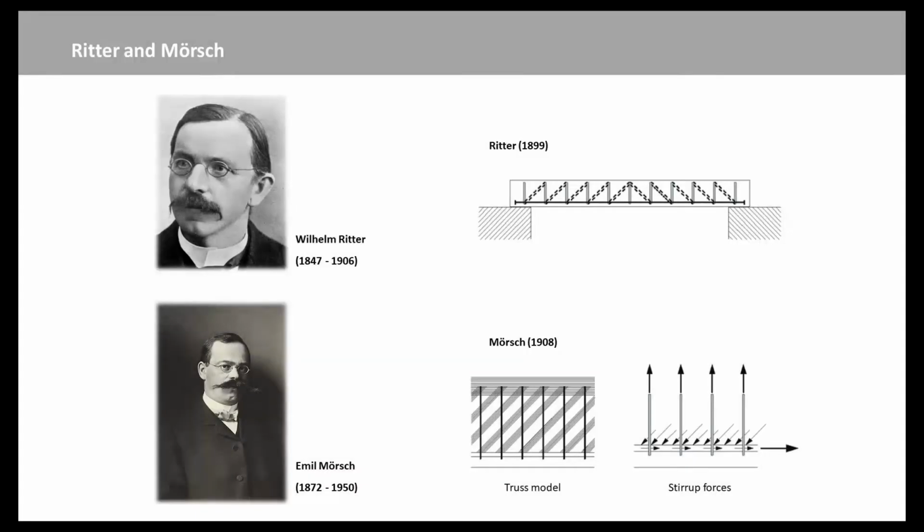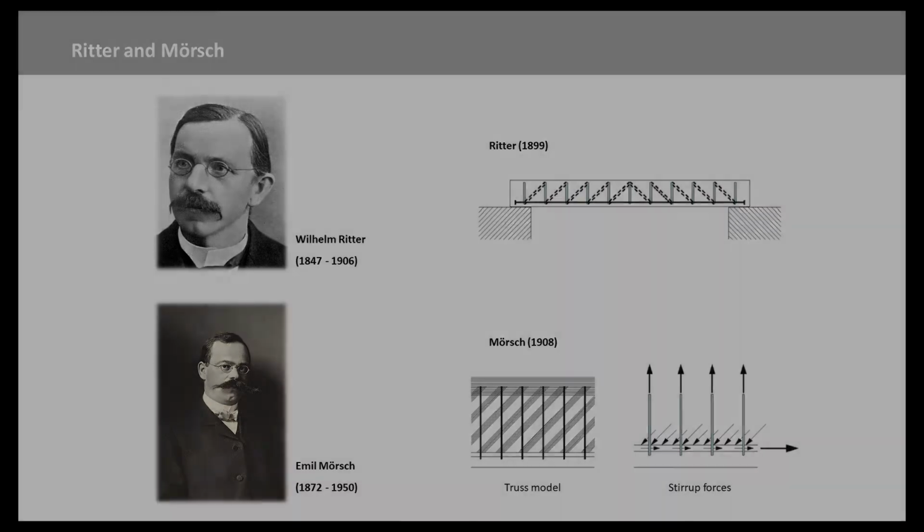The truss analogy proposed by Ritter-Mörsch for the calculation of shear reinforcement in reinforced concrete members is the oldest and best-known example of reasoning by means of strut and tie models. However, the method is also very well suited for the design calculation of compact structural members, such as foundation slabs supported by piles, corbels, deep beams, walls, and anchorage regions in pre-stressed members.